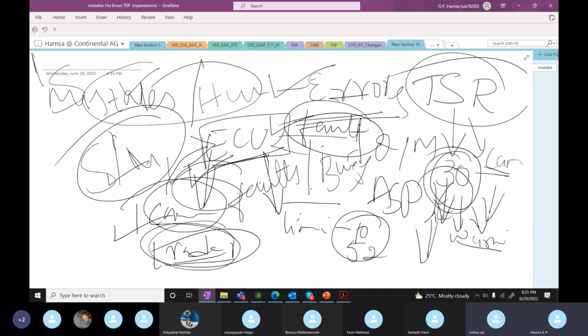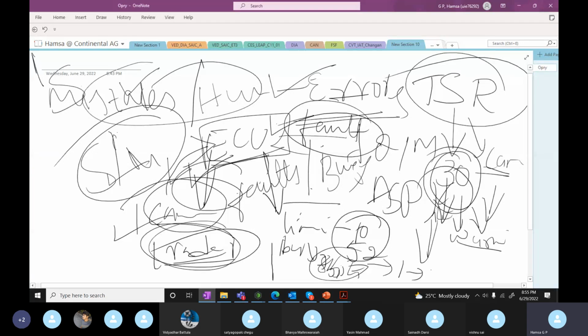Again, the ECU will set a fault and it will provide the warning indicator. For every fault, there is 1 byte of data, which is 8 bits. Of these 8 bits, 1 bit identifies whether a warning indicator should be given to the driver or not.